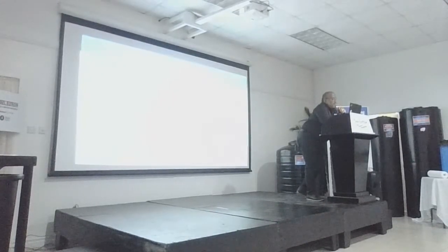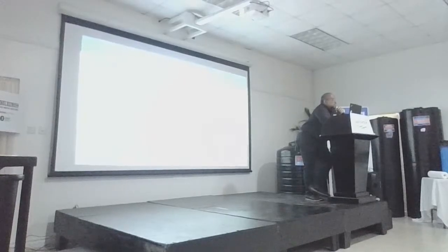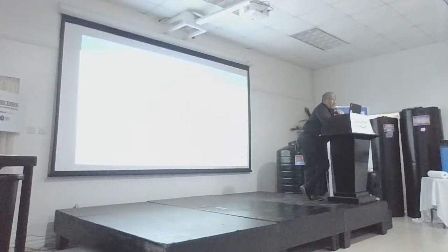So primary treatment. Primary treatment occurs through sedimentation, which involves the separating of the solids and liquids in the wastewater. This normally happens in the septic tank that you have attached to your house. Like what we've been showing here, the 750-gallon septic tank is primary treatment.